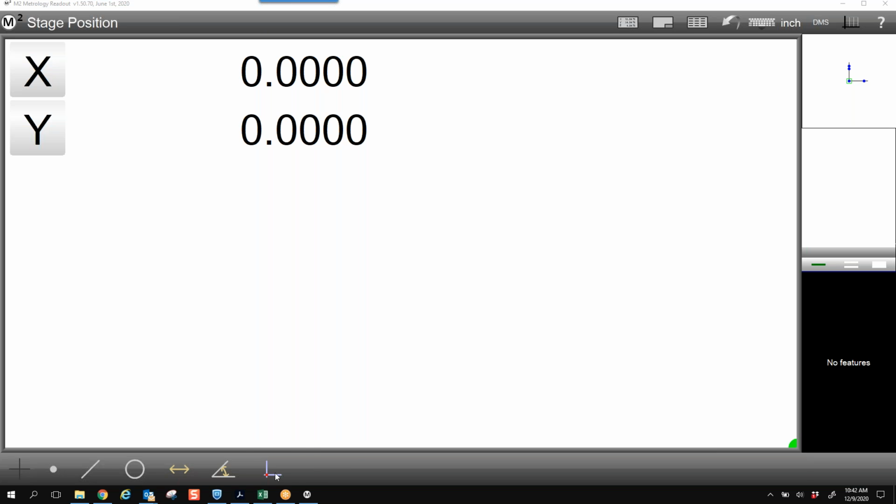So that's one of the nice things with this feature, this datuming system right here. It's nice because I don't care if the part is crooked or if it's straight. I can create, let's say, my A datum, and I can actually make that A datum, even if it's crooked, it will think that it's straight. And that's it in your part alignment. So it's nice to see it done on a part that we can manipulate, and I'll show you kind of how that works as we go.